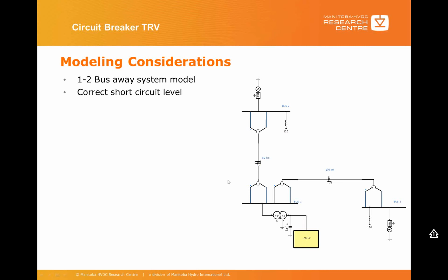Your interest may be the low voltage side of the station or the high voltage side of the station. Whatever the interest, we have to model it in detail. For example, here my interest is not the high voltage side, which is why it is represented as a simple bus. My interest is the low voltage side, so this will be a detailed representation of the station.